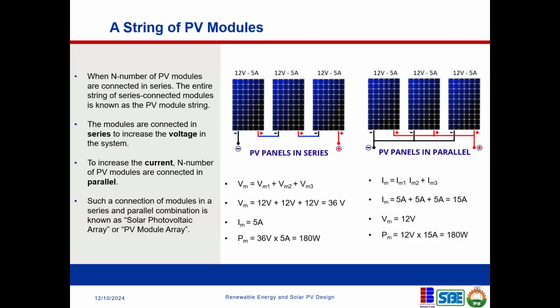Again, when you go out in the market to look for solar panels, look for those that have some high tolerance for shading. Look for those that have those connecting diodes. And that's also part of the reason why you've seen half-cut solar panels: to reduce some of those shading losses, to increase solar panel efficiency, as well as reduce the losses of the current when they move through these solar cells. I think what I'm saying now has already been explained in our initial video, but for emphasis I'm just trying to repeat it because it's important that we have that common understanding.